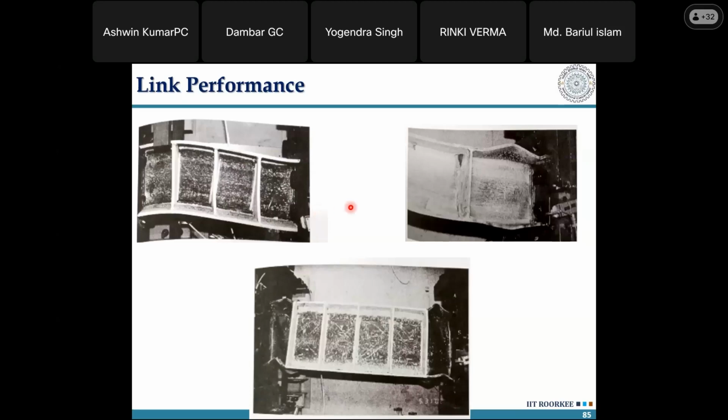If you look at the diagram closely, you will see that the flanges here have the whitewash intact; nothing has happened to them. But on each panel, the whitewash flakes have gone out. So this is a pure shear link. If you look at this particular element, you can see local buckling at the ends of the links. The shear panel here and here, the whitewash is still intact. Here, a little bit has gone off. So this is the long link, where the link has undergone flexural hinges.